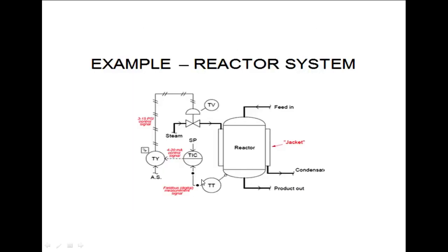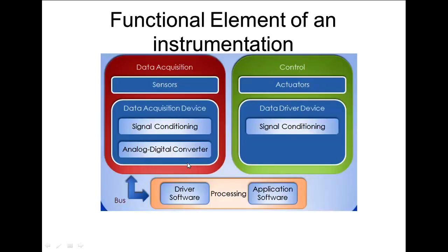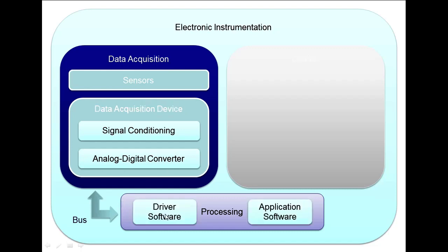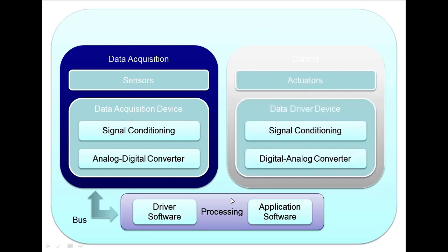Thus, this current or voltage value must be converted to digital, which happens inside the controller, or you can do it in a data acquisition card that converts the voltage or current value to the digital value of this controller. Right, so this is an element where we process inside the controller from analog to digital using a bus. Okay, this we can use software to manipulate the data.